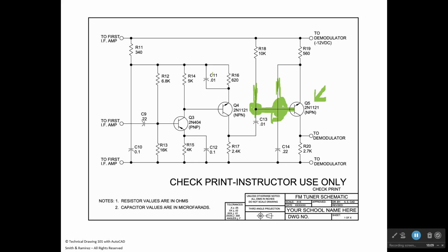So when you draw your schematic, you have to be careful, and if there's supposed to be a dot, you need to be sure that you put a dot there. And if there's not a dot, like right here, don't add one. The other thing about the dots is it's something that you're going to make a block of.